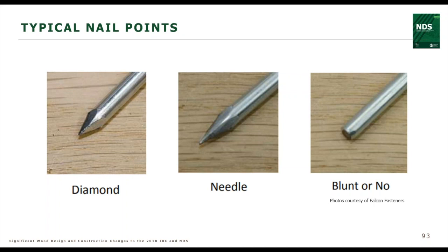And that nail tip length becomes important when you're doing your lateral yield calculations. You assume that you use 1/2 of that tapered tip length in your length calculation.